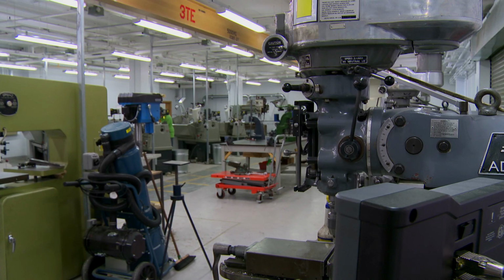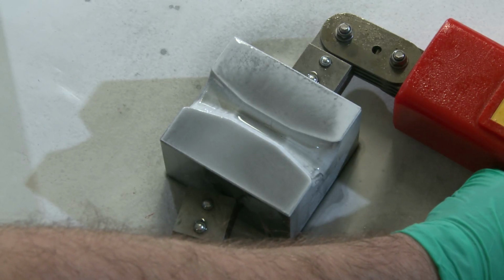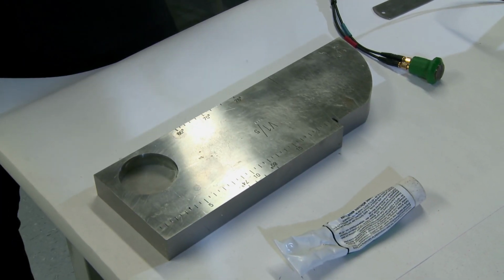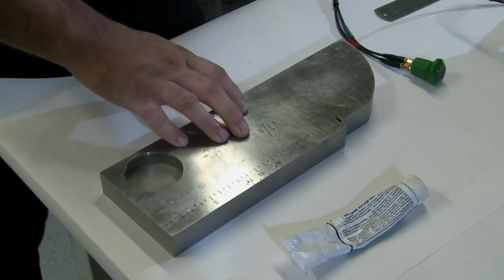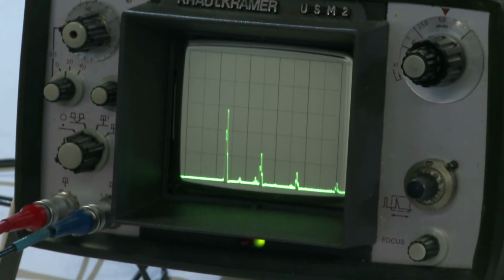Okay, just to recap then, the dye penetrant test allows us to detect surface breaking defects. The magnetic particle inspection allows us to detect slightly subsurface defects. And what we've got here is ultrasonics, and that allows us to look right inside the material. So this is a sample. This is an ultrasonic probe, and this is where we can see the signal coming back and detect any potential differences in the material. So this is exactly the same sort of technique you'll see in a hospital, maybe looking at babies, maybe looking at kidney stones, that sort of thing.